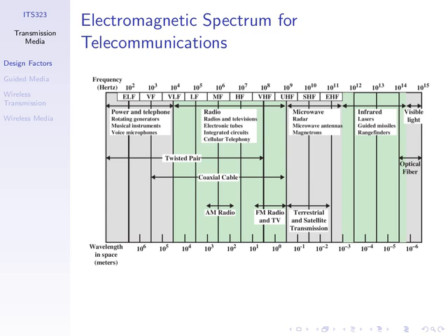The next radio channel on the spectrum would have a similar signal, but at a different center frequency, representing a different channel. So all the FM radio channels occupy some portion of the spectrum around this area, around the 100 megahertz, plus or minus several tens of megahertz. So similar with AM radio and TV, that's a similar arrangement.